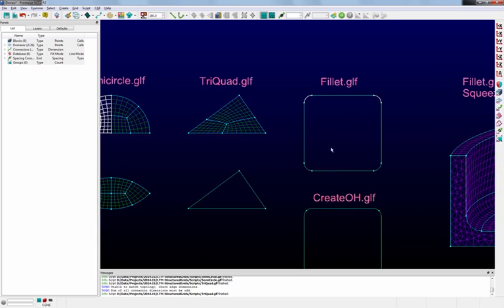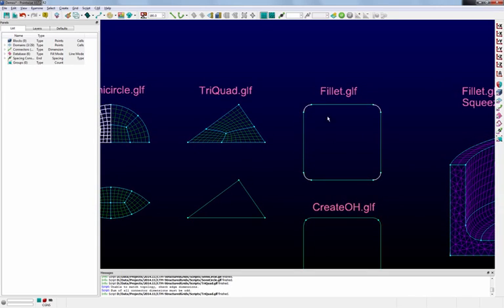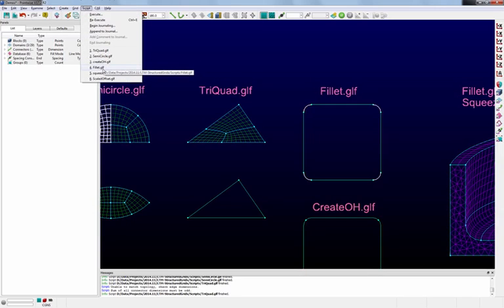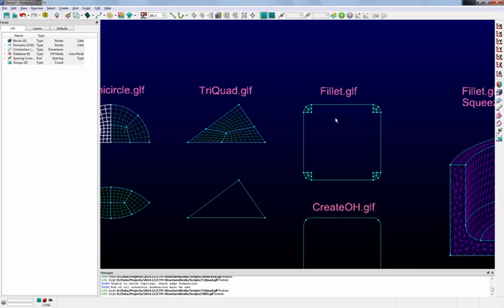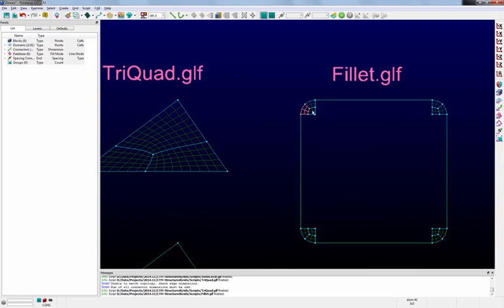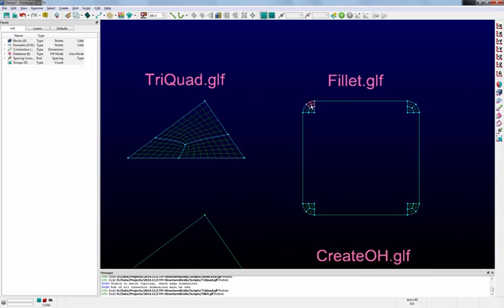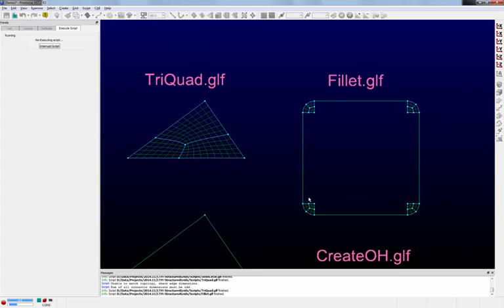The first thing we're going to do is create these little corner blocks, as I call them. You simply highlight these connectors here. You then go to script and run this script that I've named fillet. Whenever we run this script, it's going to create these quadrants for us based on the local curvature. Then we can run another script that I'll talk more about later that will take these other connectors and fill in. We simply highlight the connector, run the script, re-executing with Control E here, and then create this internal topology pretty quickly.